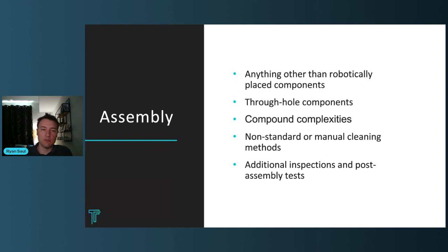You have to use a stencil that is thin enough to apply the solder paste minimums that you need to be successful in SMT without bridging on these micro BGAs and 01005 style packages. And yet also be thick enough for these heavier, more mechanical or thermal connections. In many cases, the only solution to that is a stepper stencil or 3D tooling, which is more expensive. So if you can avoid including these heavier elements and these super fine pitch elements on the same boards, that's ideal. Separate them into two boards and you save a tremendous amount of money, engineering time, potentially quality risk as well.